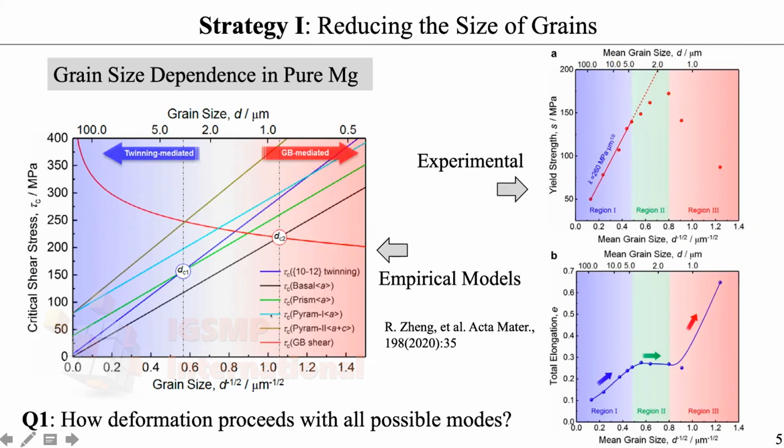And if we look at other slip systems, what we call the prismatic slip, here is the grain lines. You can see at the larger grains there is at least 50 times difference. But if we go to the really fine grains here, it's rather about the same values, about 300 and 330, that difference.